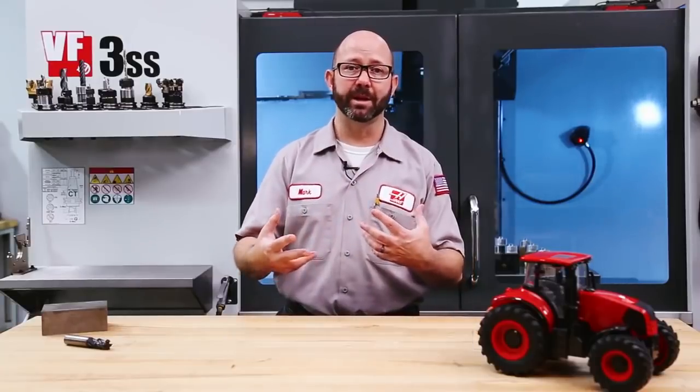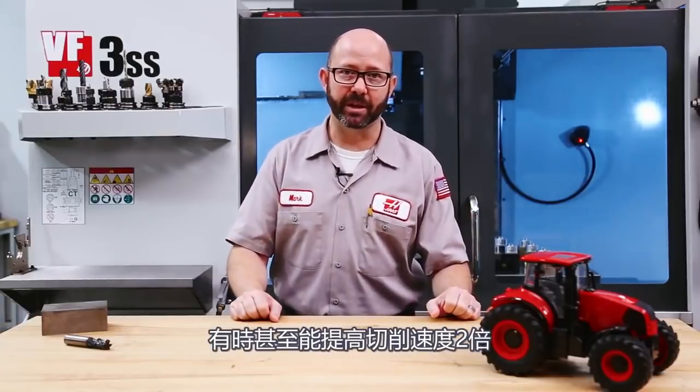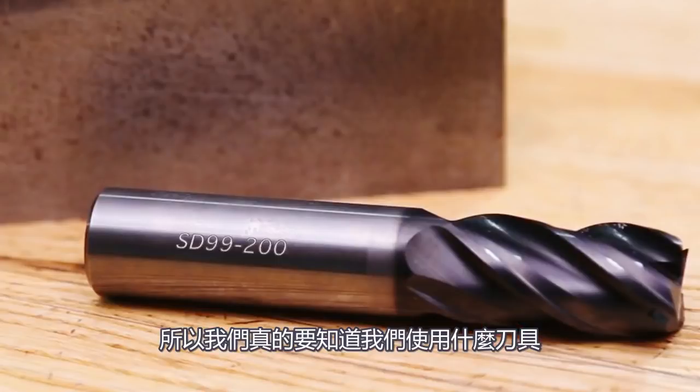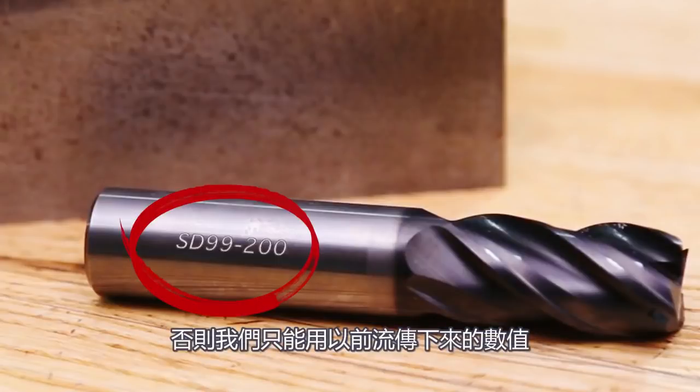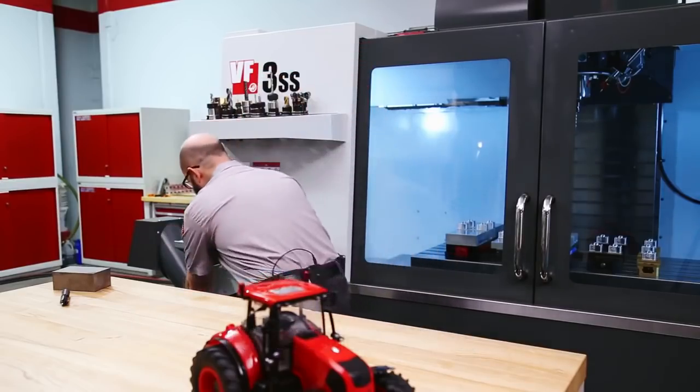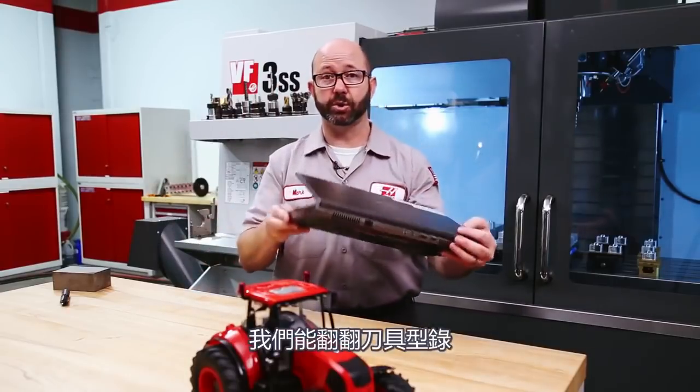Now, in the good old days, all we really needed to know was whether our end mill was high-speed steel, carbide, PCD, or CBN. Those days are gone. Today's tools have coatings on them that might double their allowable cutting speeds. So we really need to know what tool we are working with. Otherwise, we'll have to use really generic values, which are pretty wimpy. With our exact tool number in hand, we can go to our tool catalog.